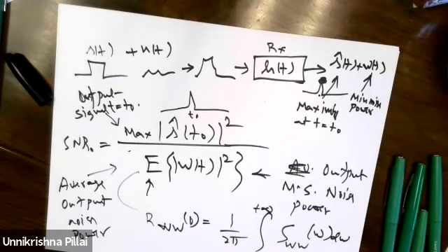Compression. I gave you one idea before, which is to multiply by a filter that will make the output flat. You can try that too. The easiest answer is 1 over S(omega), but that may not be implementable, and usually you want to do it with a finite length filter. Otherwise, theoretically, H(omega) is 1 over S(omega), so that the output spectrum is flat and the output waveform is a delta function.